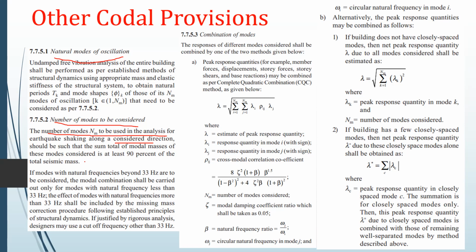We talked a little about this modal mass participation factor in our previous lecture videos also. When due to the ground excitation, our building or our structure vibrates in a particular direction, not all the mass is contributing to that vibration. Only a certain amount of mass is contributing to the vibration of our structure in any particular direction, in any particular mode of vibration.